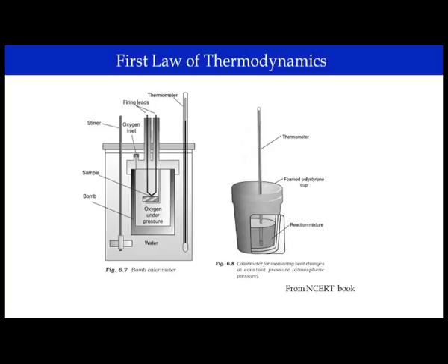Now, this entire bomb is kept in a surrounding water bath, which is again sealed by an adiabatic wall. So, any change in temperature in the surrounding, means in the water bath here, can be measured by the thermometer, and there is a stirrer also used, just to make the mixing or the temperature uniform.